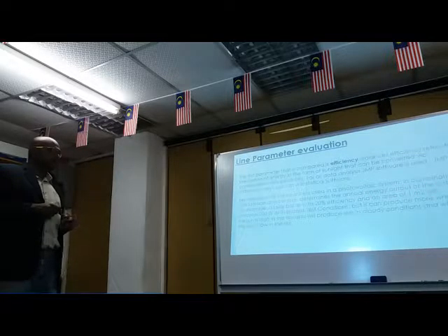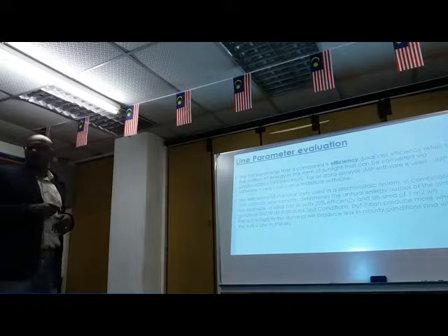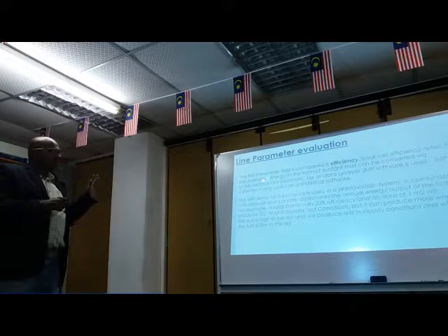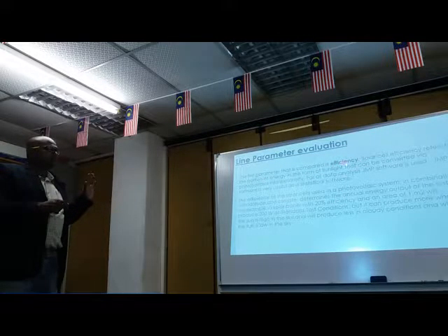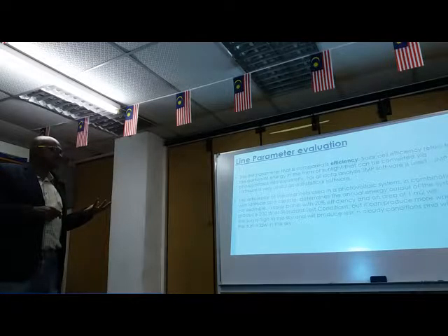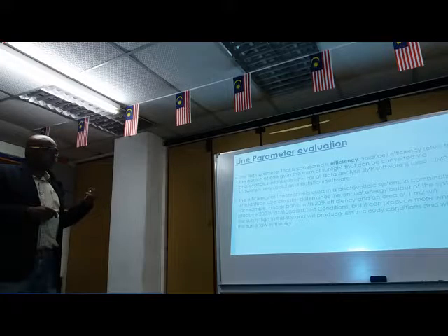For example, a solar panel with 20% efficiency and an area of 1 square meter will produce 200 watts at a standard test condition, or STC. This is how we test our solar panels. And the most important takeaway point from here is the word efficiency. Whoever is in this industry will emphasize efficiency, because efficiency is the ability of the product to absorb sunlight.